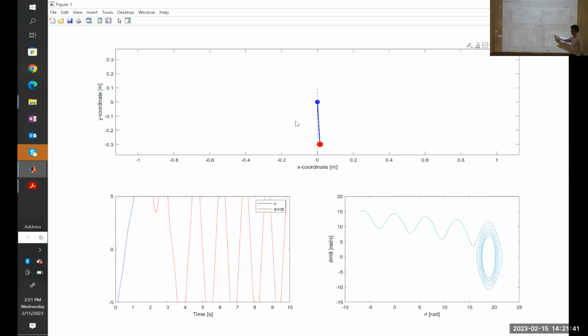Takes a long time to reach this area. We call this the region of attraction. The system gets close to the stable focus and is being trapped by that, and the trajectory is attracted to that point and finally will converge to the equilibrium point. So when we are in the region of attraction, this will also take longer to stabilize.